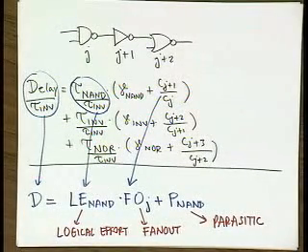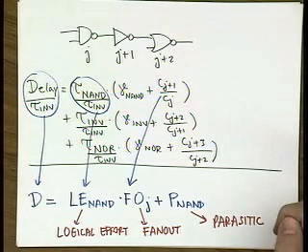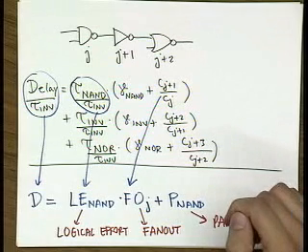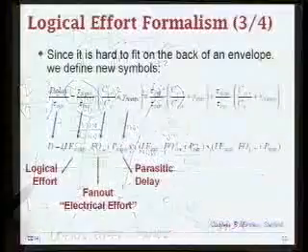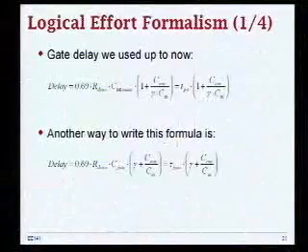What logical effort tells you is basically the ratio of the total input capacitance of a gate to the input capacitance of an inverter, such that you have the same delay from that gate as in the case of an inverter. Or you can look from the other perspective. If you have the same input capacitance, how much worse is your delay, from the perspective of the pull-up and pull-down resistance, than your ideal inverter? Because we know the inverter is the best driver we can have, and we can quantify all other gates relative to the inverter case. So let me now switch to slides and review all these steps.